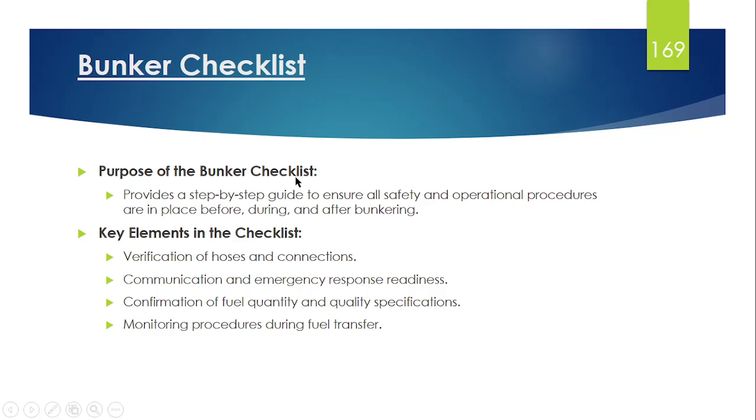Certain points will be written which we need to check before bunker, certain points which we need to check during the bunker, and after the bunker is finished we need to check certain points. So it provides us step-by-step guidance on what we need to check in each segment, each sequence of the operation. Okay, so that is the importance of the bunker checklist.